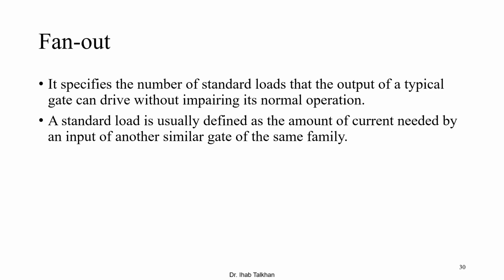Actually, this slide and what comes next describe what I mentioned in the previous slide about the fan out, the power dissipation, noise margin, and delay. The fan out described here specifies the number of standard loads that the output of a typical gate can drive without impairing its normal operation. The standard load is usually defined as the amount of current needed by an input of another similar gate of the same family. So this is what's meant by fan out, and I described it in my previous slide.